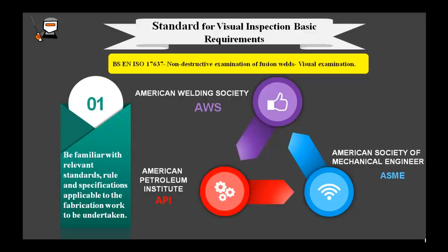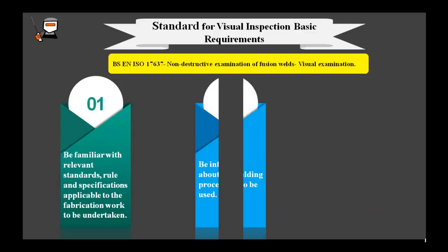Now we should move to the main topic. When structure and pressurized items are fabricated by welding, it is essential that all the weld joints are sound and have suitable properties for their applications. Control of welding is by WPS that give detailed written instruction about the welding condition that must be used to ensure that the welding joint has the required properties.